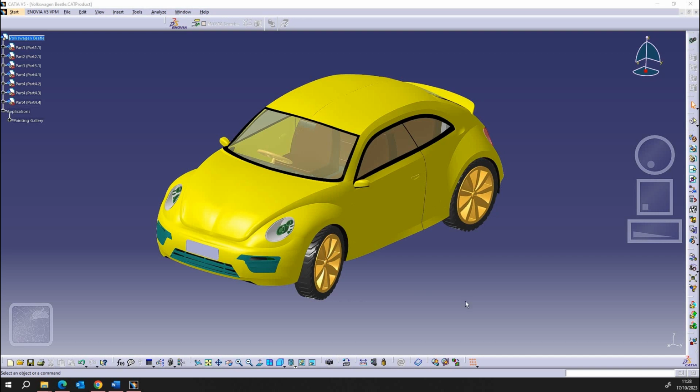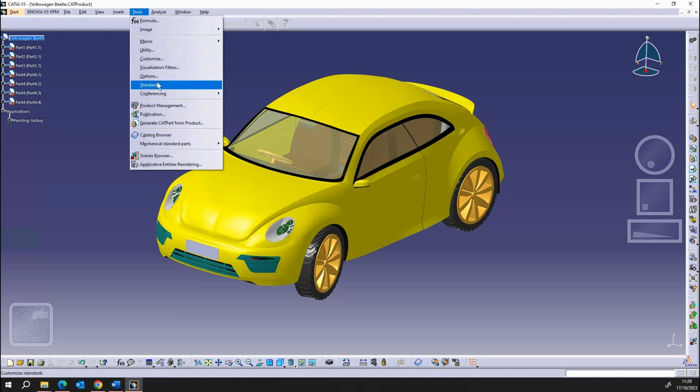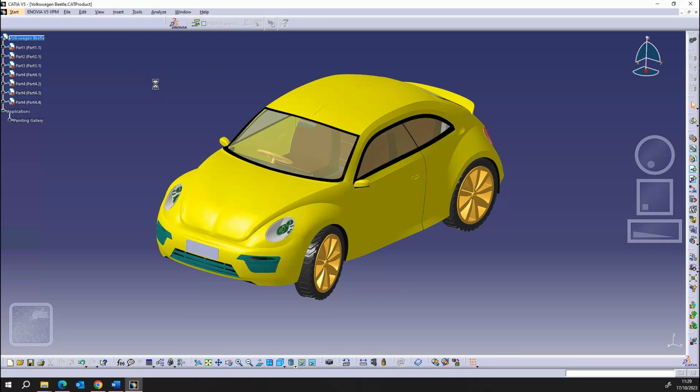Here I'm going to show you how to take measurements, sectioning and measurements basically. So now I want to take the measurements of the door to the rear panel body. It's important to also note that when you're taking the sectioning, it's going to either export it in polylines or as a curvature. You need to be sure of which of them you want to use because depending on which you export it as, you will be able to measure it easily or you have a lot of dots.